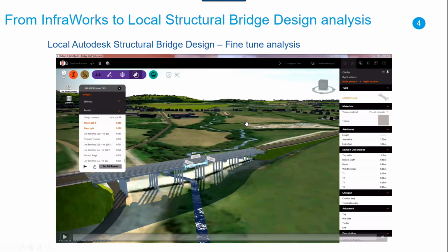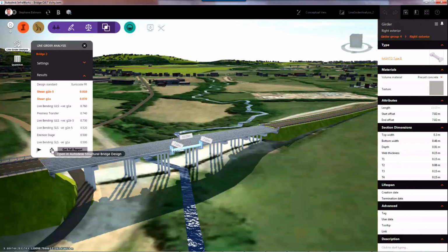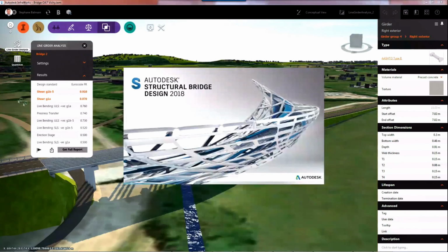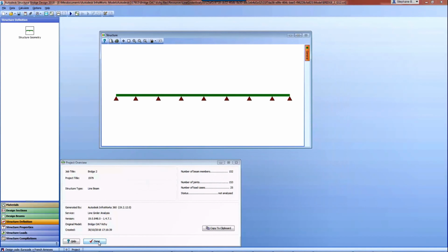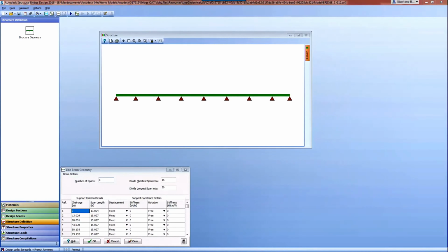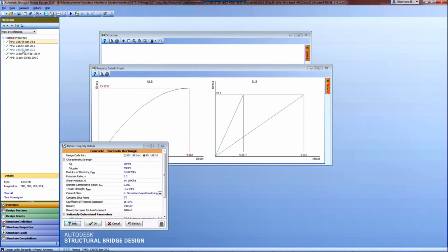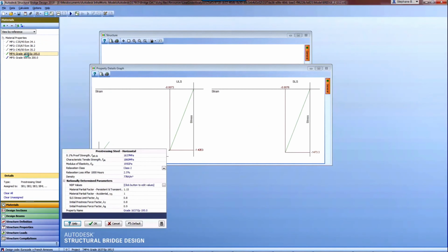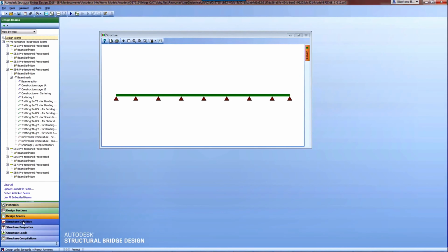So what I will do, I will download locally the structural redesign file. And after, here I can check and set everything. Here you have all the spans. Here you have all the materials. Okay. So if you wonder what calculation is done in structural redesign, you can have a look here or in the calculation notes.